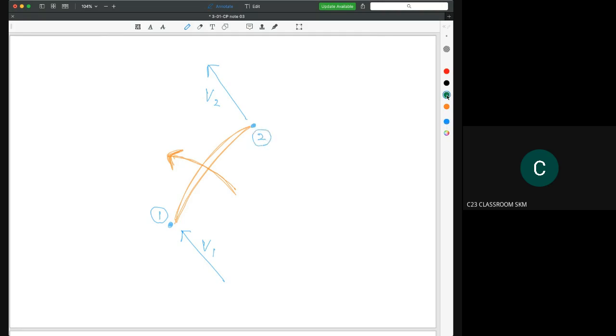Okay, the third step is you draw velocity according to the design of the blade, the design of the pump. So there are two designs. One is about the blade and one is about the impeller. So then we draw the velocity relative to the shape of the blade. Because the shape here is like this one, so now we draw the VR1 like this. And because the shape is something like this, for sure the velocity flows like this one. So we draw it as VR2 like this one.